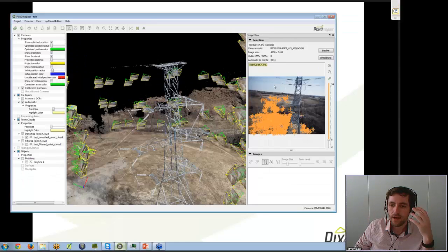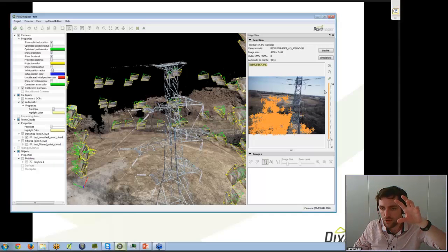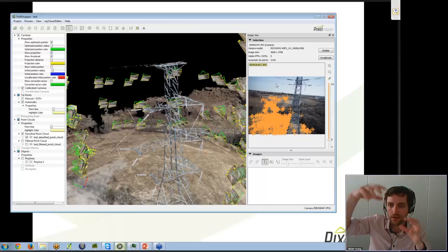The sky has basically no features. So as soon as your oblique imagery starts to be too oblique and contains a lot of sky, all these pixels are wasted because there cannot be any features computed on them. So the more your camera is watching the sky, the fewer features will be extracted from this image.